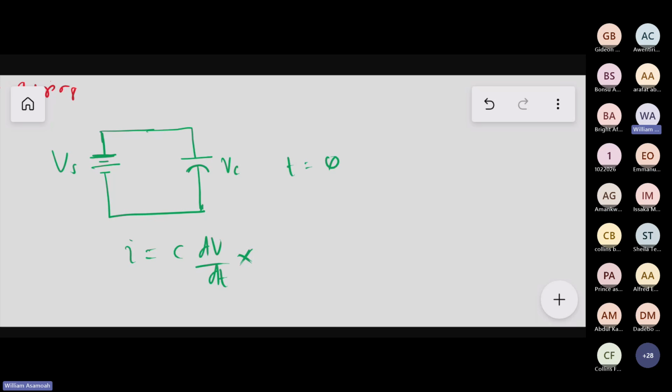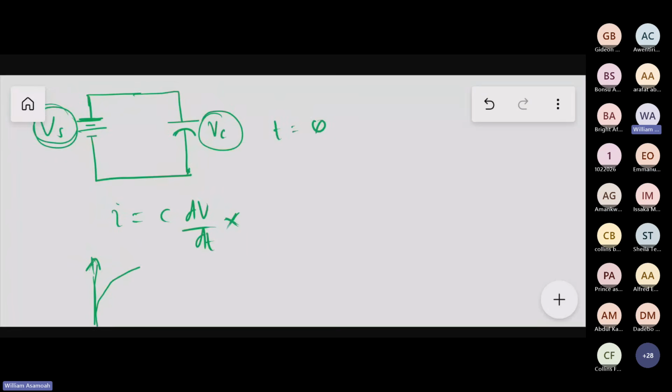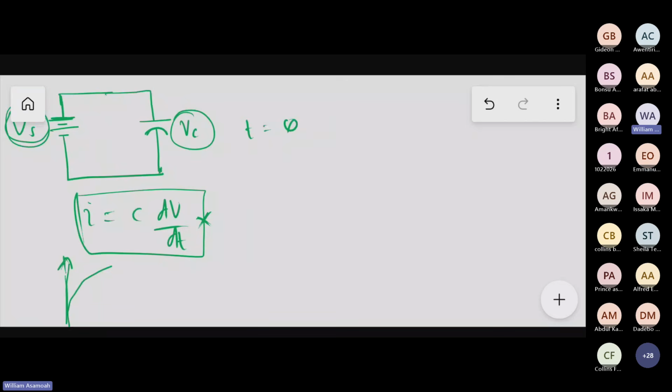So what happens here is this. All the voltage of this source appears across this capacitor. Now we're saying that capacitors would gradually rise, but when you connect it to a source and it's at 0, all that voltage appears across it. And it can't instantaneously take all that voltage in as charge. Do we understand? This equation wouldn't work at that time.